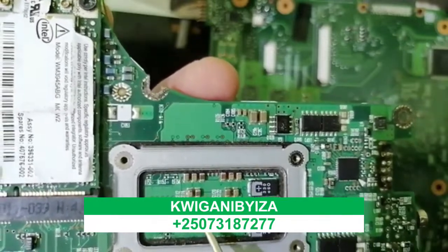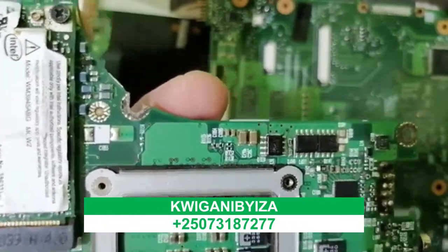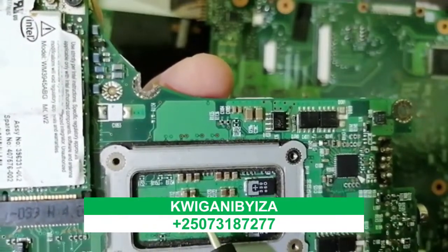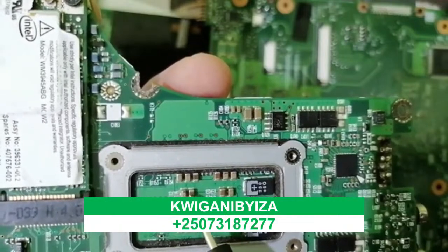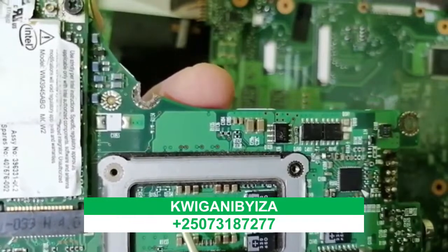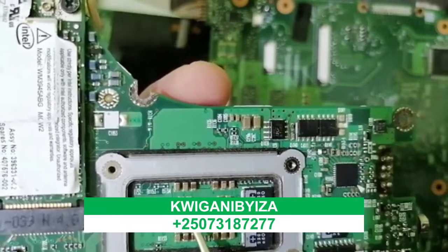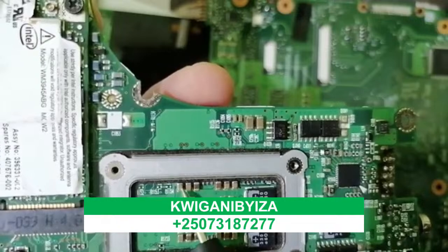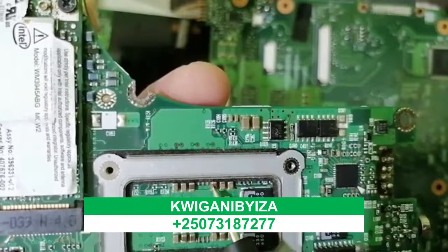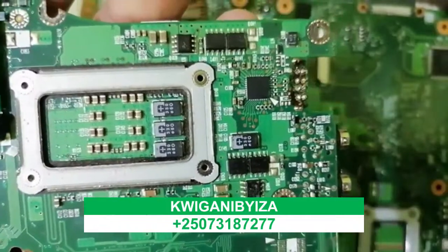This, for example, and this are the same, okay? But as you can see, this one and this one are not the same. This is a brown color, and this color is not like this one. Those over here are also not the same as this one. So, for example, if this one is failed, do not replace it with this one or this one. You should replace it with another one. For example, these two are the same. These two here are the same. This one, no. Okay, so this is how you can replace ceramic capacitors.